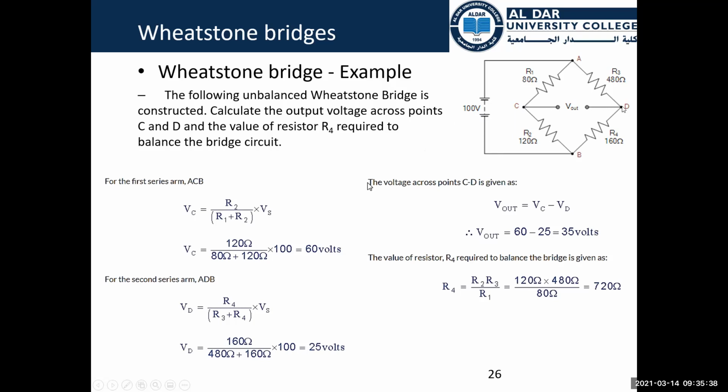What about VD? VD is also the same. It is 160 over 480 plus 160, and multiplied by the voltage source, which is 100, to get 25.